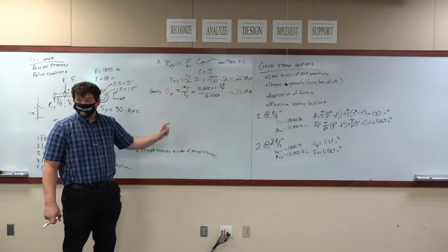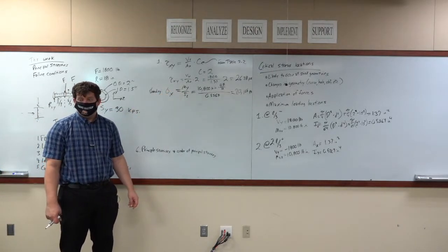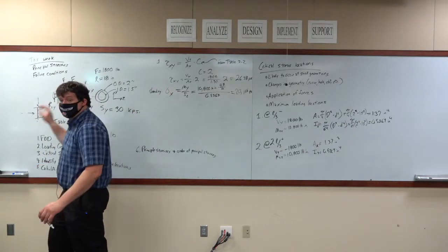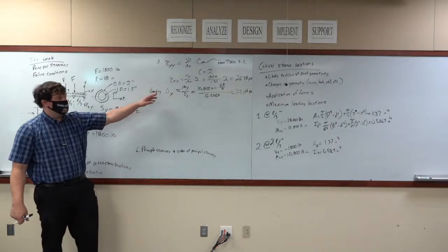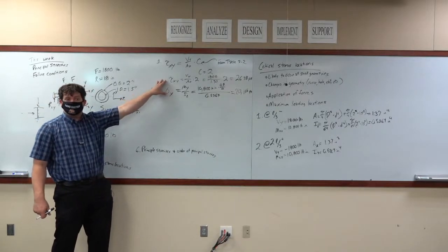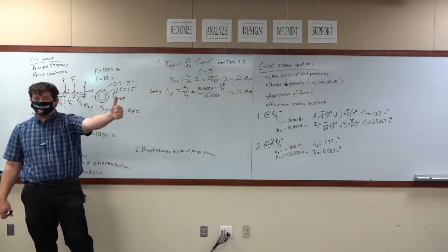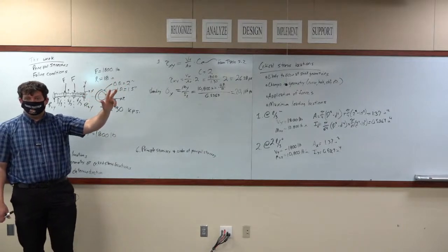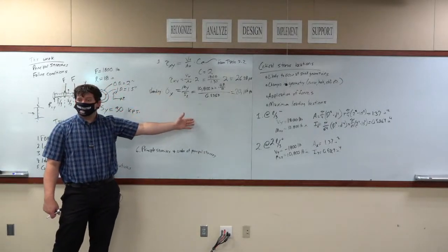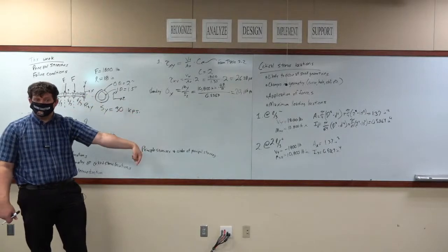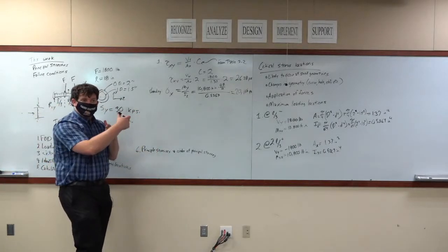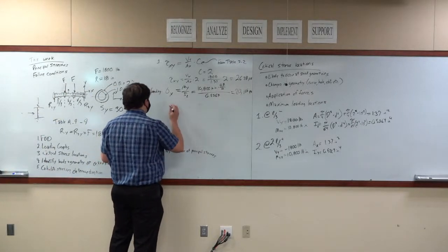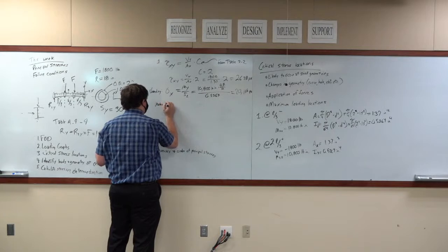It's in the y and the x direction. Both show up. I was also talking about the loading, like force. Oh, this actually doesn't matter. Okay. This is what matters. Do we have any z component here? We do not have a tau xz, we do not have a tau yz, and we do not have a sigma z. Which means we are dealing with planar stress conditions, which means we can use Mohr's equation instead of using that gigantic 3-dimensional equation, which is gross. Okay? So, Mohr's circle equation.